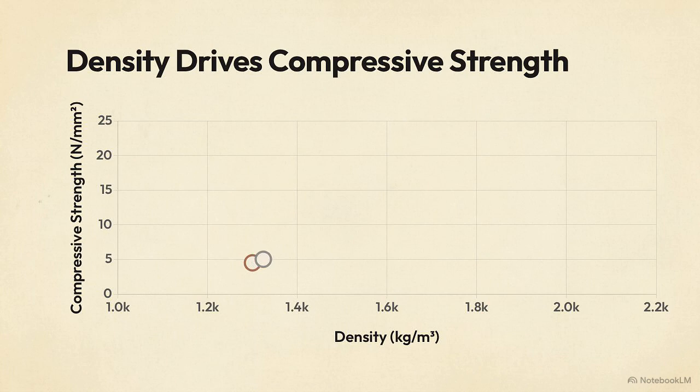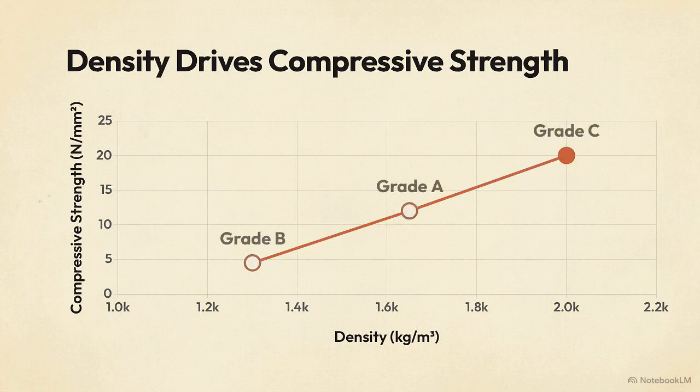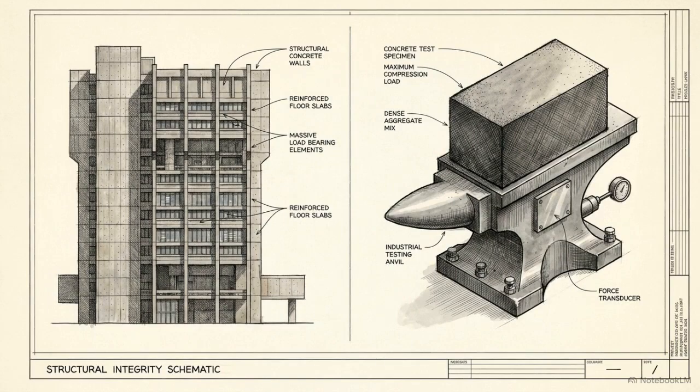Grade C units are strictly solid concrete blocks. These require the highest minimum density, exceeding 1,800 kilograms per cubic meter, to achieve their structural capacity. The minimum average compressive strength a unit can support scales proportionally with these density thresholds. This grading matrix forces structural engineers to explicitly match the unit density to the specific calculated load of the building.